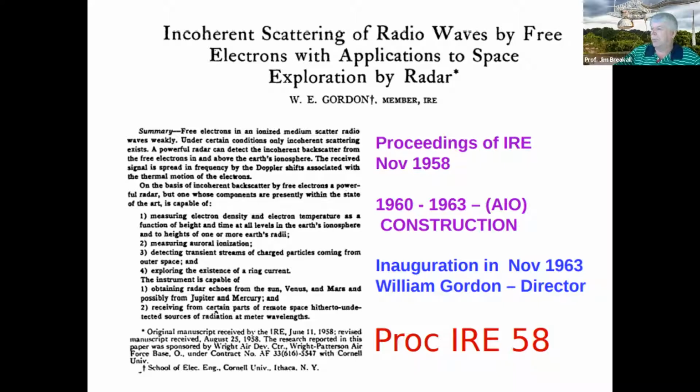And then in the shortwave frequencies, 3 to 30 megahertz, the radio waves can get bent, and you think of them being reflected off the ionosphere, and that's how you can have radio waves travel long distances at those frequencies. But if you go high enough in frequency, the radio waves pretty much go straight through. They don't get bent back to Earth.